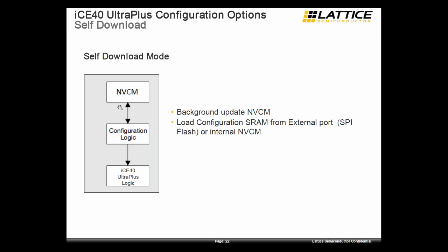If the device is configured through NVCM, that can be bypassed, as mentioned before, through the SPI interface. And the device can be reloaded through a SPI interface using a microcontroller or our programming hardware.